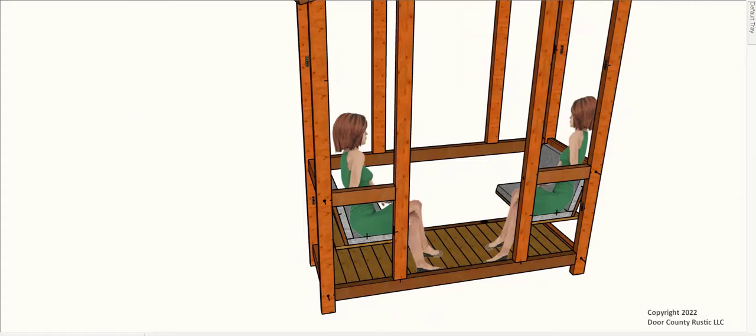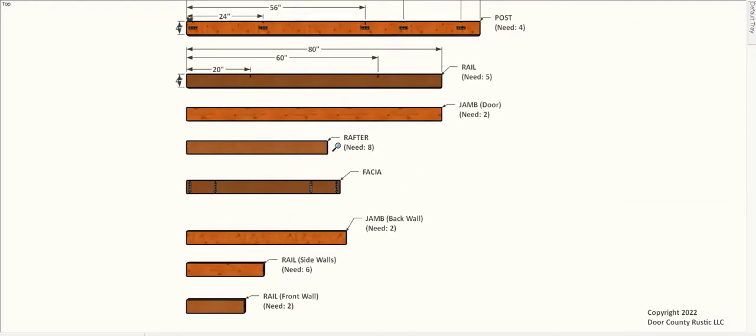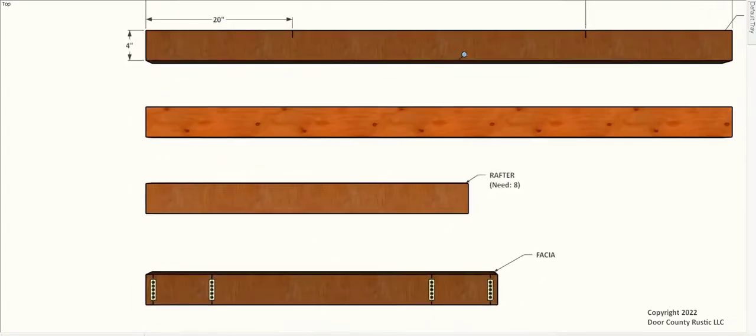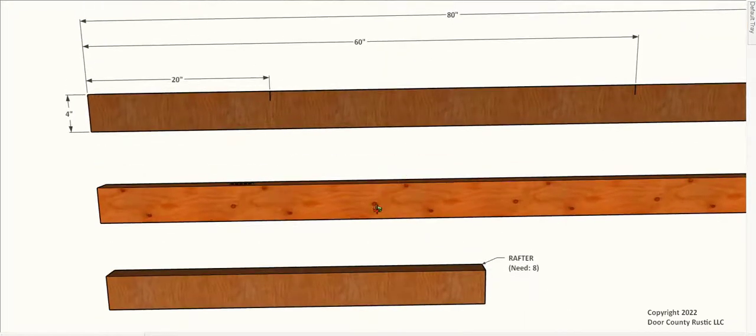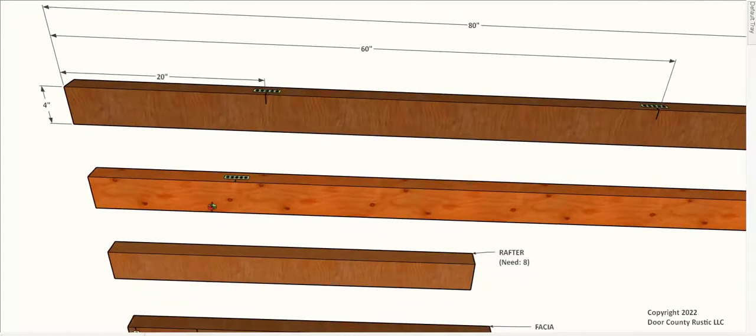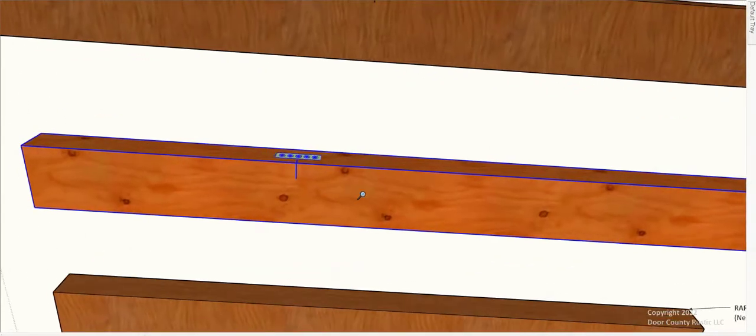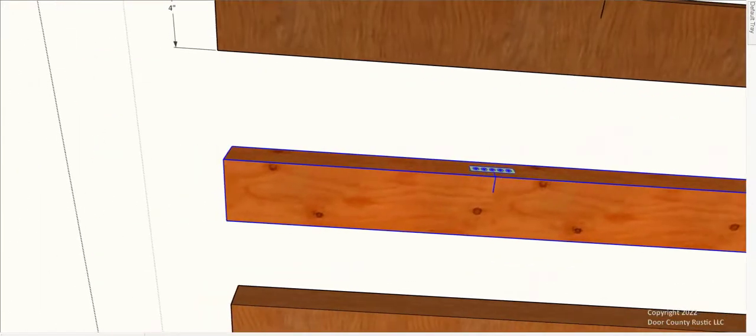So now if we go back to those cuts in the cut list and we look at that, again, this is the jamb. Now I'm going to go up to there, and the only one that I have is right here. So it's just that one right there. So to dimension that, I'm going to go to the, again, left edge, come up, and I've got a 16-inch dimension to the center of that.